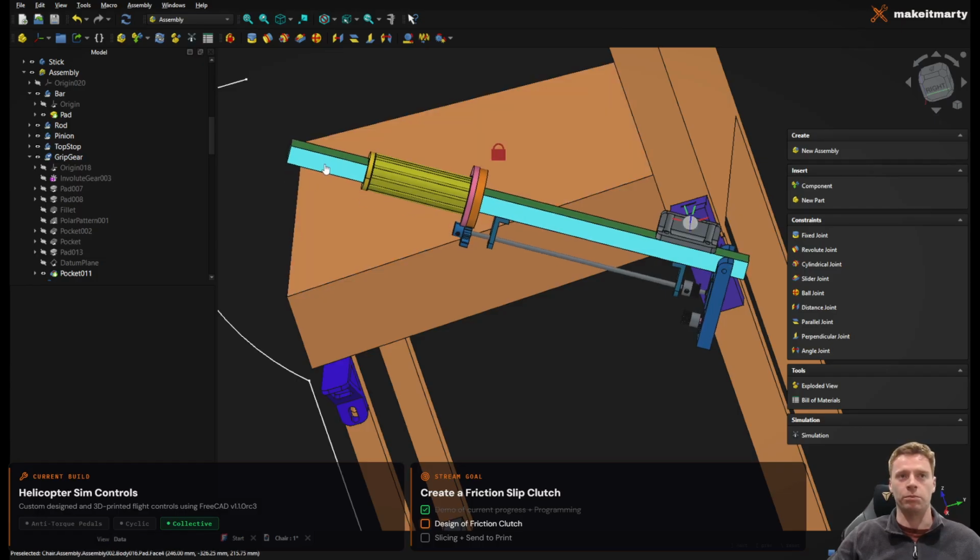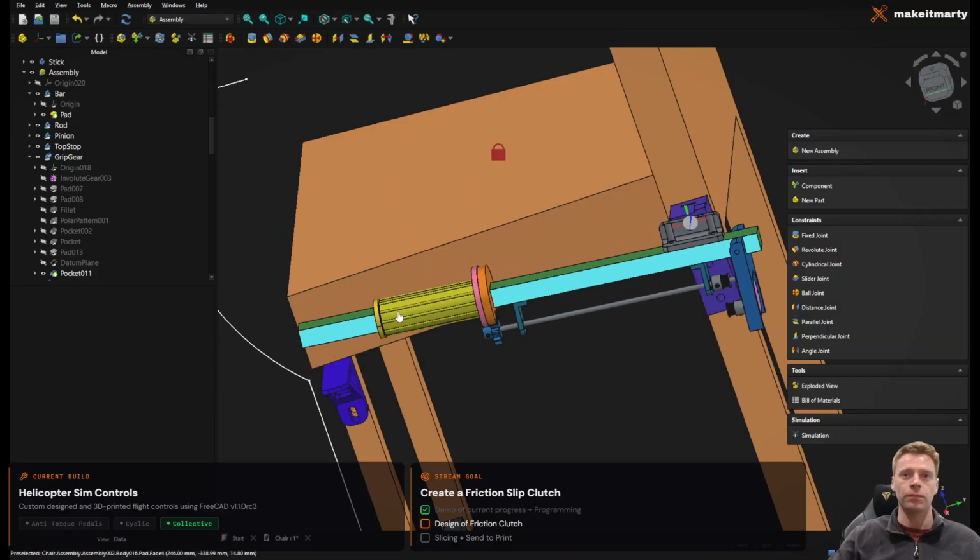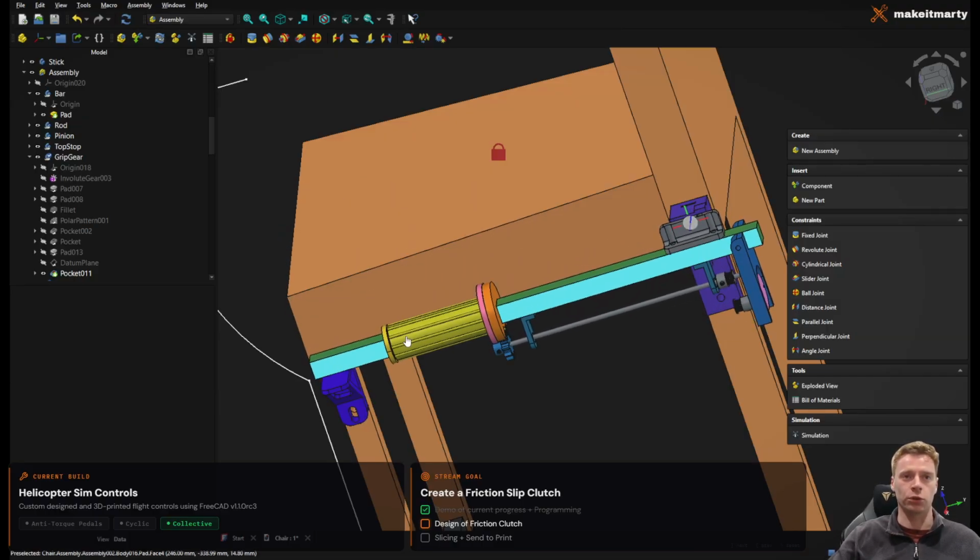If you were to be in the air and then you just close the collective quickly, it will require less throttle. You'll see the RPM start to rise slightly. The governor will take out that throttle. And that's basically a PID controller loop where you have an input, an integral, and a derivative. So yeah, auto-controlling the throttle basically.